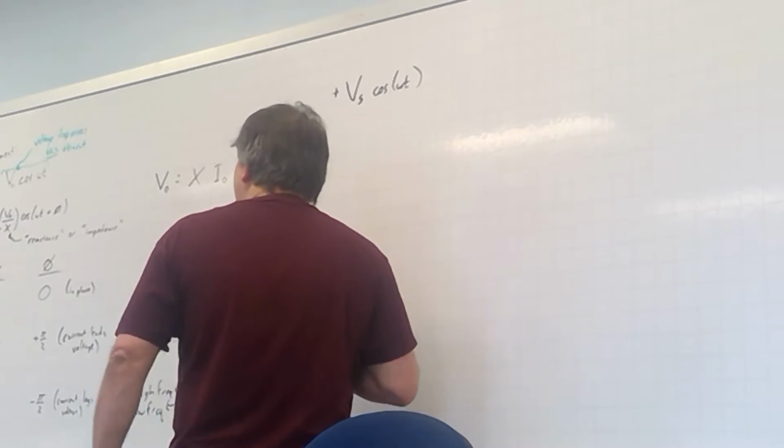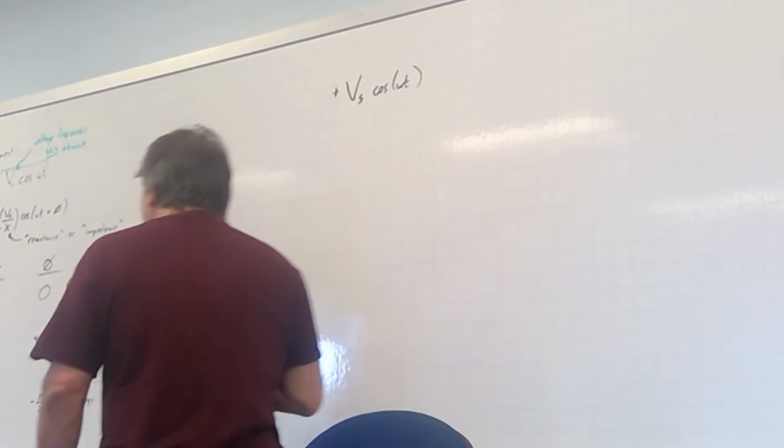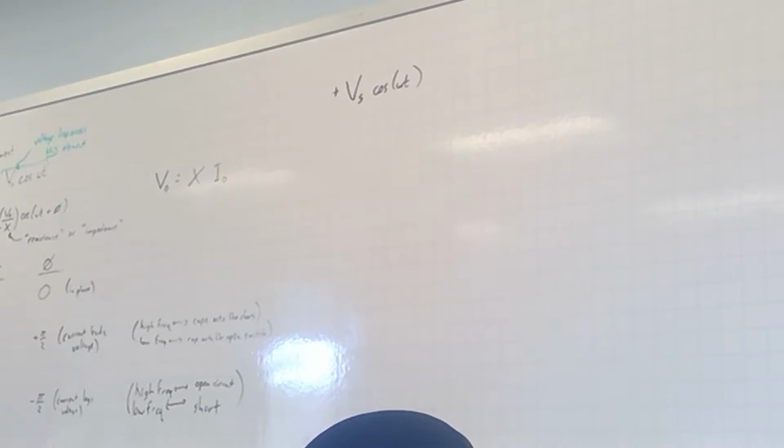What happens next? I hit that resistor. And if I'm saying this is my canonically positive voltage terminal, then I will also say this is my canonically positive direction for current. Again, what do I mean by canonically positive? I mean, depending on what moment in time I read this, the current may or may not be going that direction. But if I tell you, oh yeah, this moment the current's positive 3 milliamps, I mean that it is going that direction.